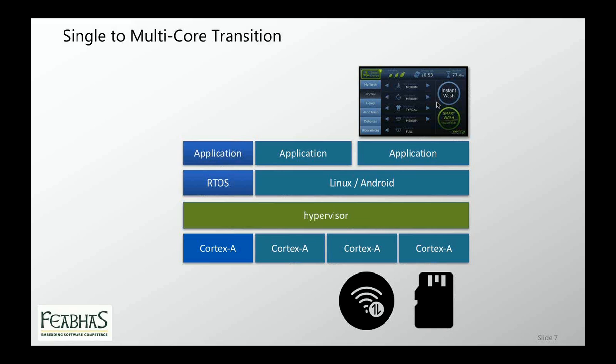So if we had a 4-core Cortex-A system, we can dedicate one of our cores directly to the RTOS, so it's still running in an asymmetric, single-utilization model, giving us the power and performance dedicated to that and controlling the interrupt channels. But then using the power of Linux with its symmetric multiprocessing, SMP, to further utilize the other processors, but still give us the power and performance model that we require for a real-time application.